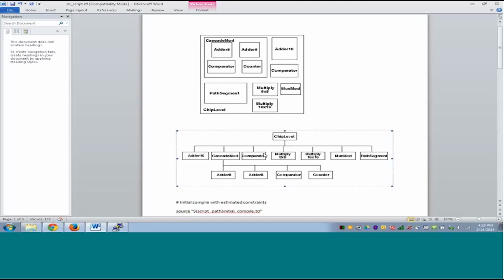Irrespective of the method, the method is exactly the same. But in the characterize-and-write-script flow, the correction of input and output delays is done by DC. When it comes to big chips, characterize will be very time consuming. So we are doing this process kind of manually, and sometimes manual works better than automatic, for example in this case.